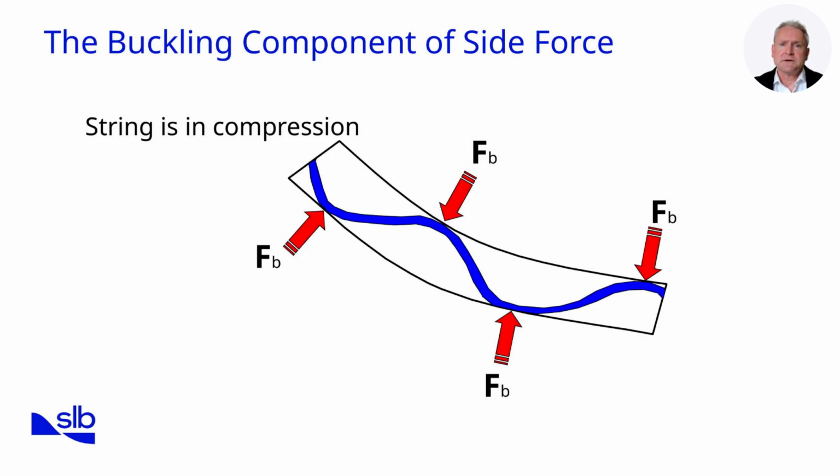Buckling can be a significant problem in directional motor drilling. It can result in being unable to slide with the motor assembly through a dramatic increase in drag. In addition, the effects of tool joints with slim pipe may have a significantly reduced impact on buckling resistance.